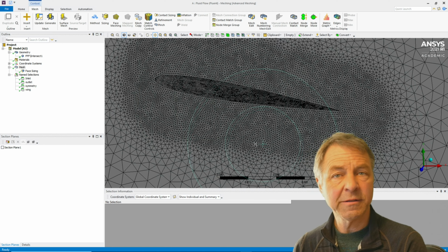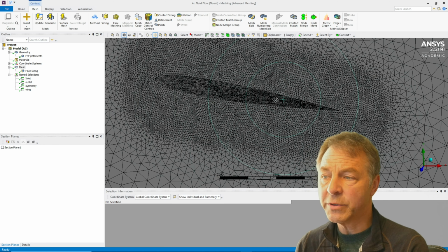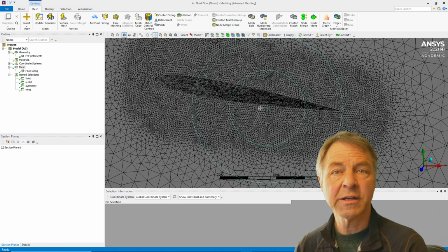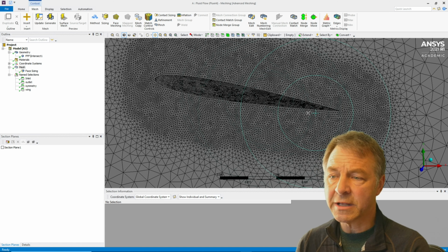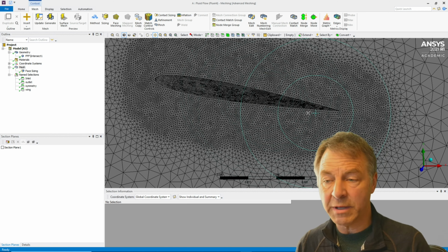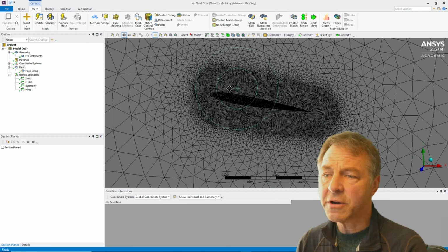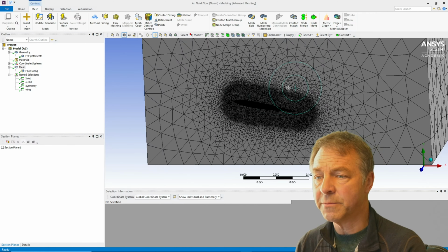And you saw in the SolidWorks simulations that if we didn't get to a reasonably small size of grid points at the wing, then the simulation didn't make any sense. And so I've started off with that presumption here in ANSYS.